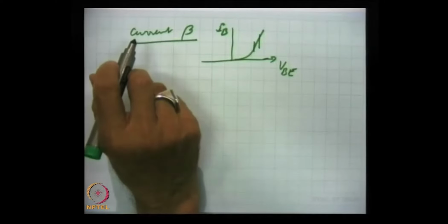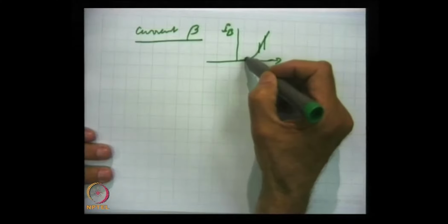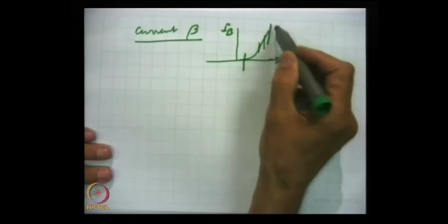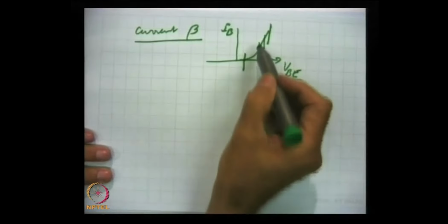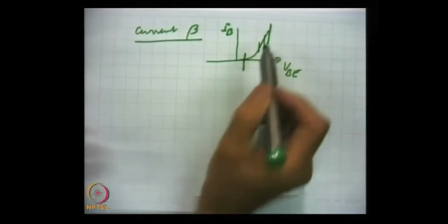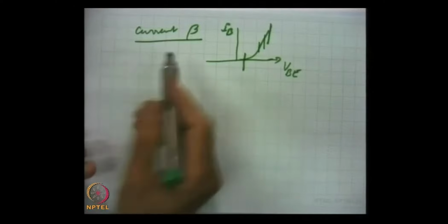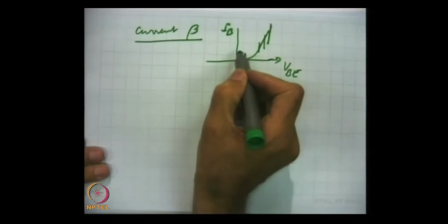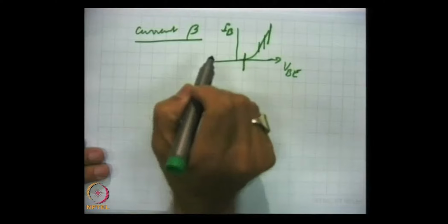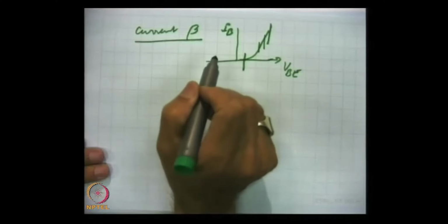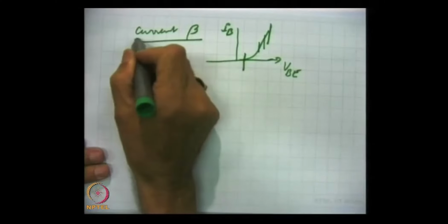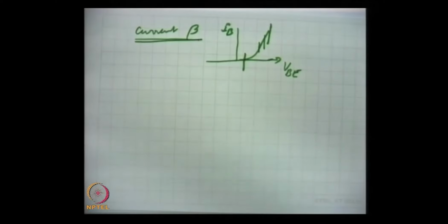But when we talk of power amplifiers, large signal, that means the whole region from here to here is involved, and the slope is varying and there is a lot of non-linearity involved. Therefore, it is important that the way the power amplifiers are analyzed is different, because we can't use these parameters as we have done in the small signal analysis.